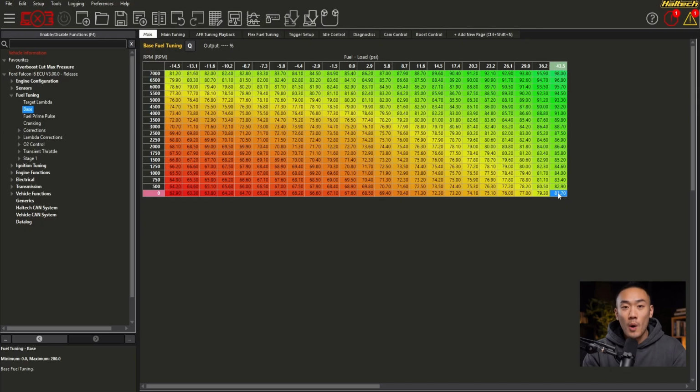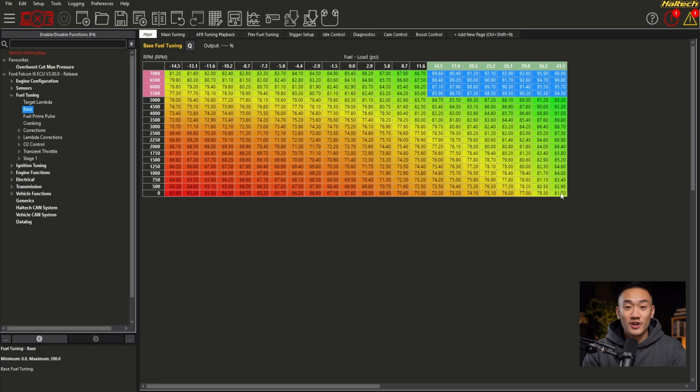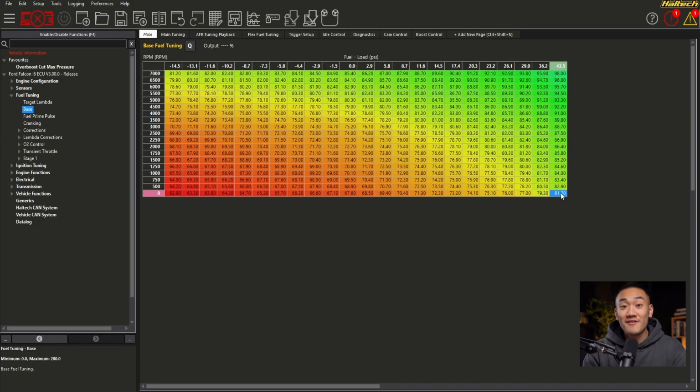Now let's look at wide open throttle. At WOT, a naturally aspirated engine will usually peak around 85 to 100% VE. A well-designed engine may exceed 100% at peak torque due to dynamic airflow effects. Turbocharged engines can show VE values well above 100% because manifold pressure already accounts for boost, and VE reflects how efficiently the engine is using that pressurized air.